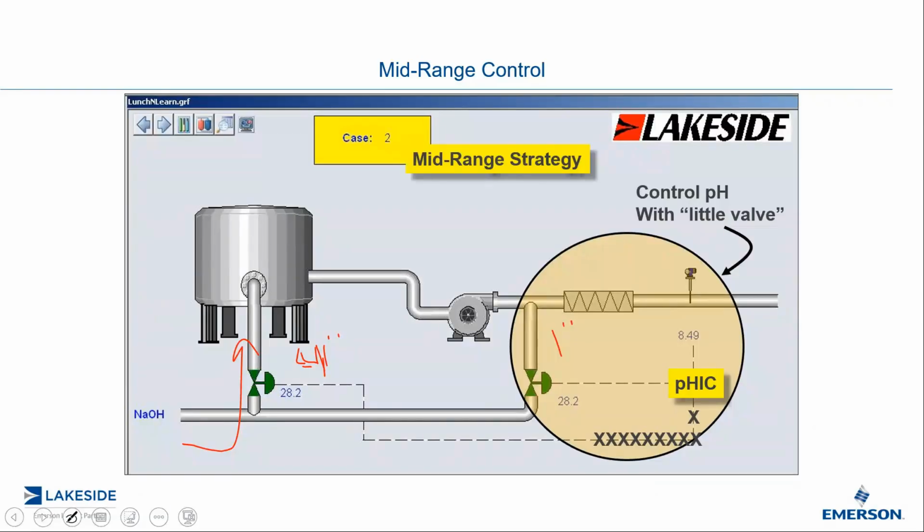But the production throughput here can vary quite a bit. That means there's a high turn down ratio between grade A, let's say, and grade B. We could be operating at, I'll make up a number, 100 gallons a minute going out, and then grade B could be 500 gallons a minute, a 5-to-1 ratio or a 10-to-1 ratio. And once again, trying to control the pH with that one valve can cause some issues because little brother can get into trouble.